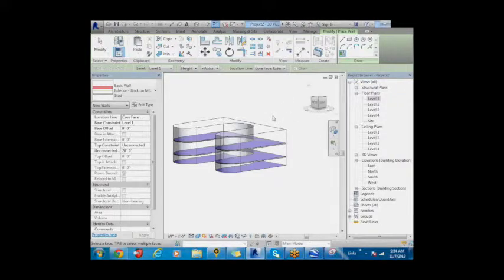When you click on the walls option, Revit is smart enough to understand that it can let us choose only wall faces now. So if I just hover over it, I'll be able to select different wall faces. I won't be able to select the floor. So I want my wall here, here, and here.